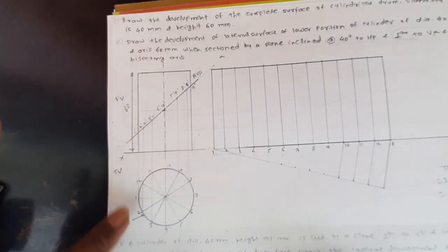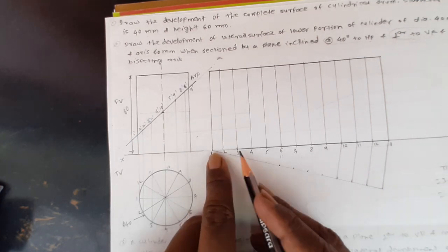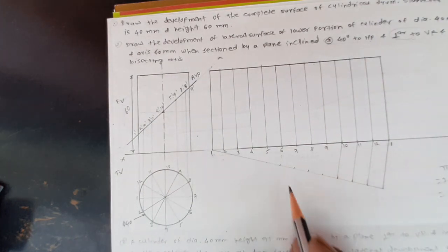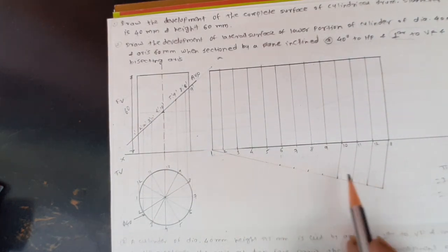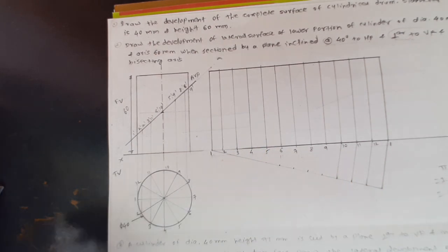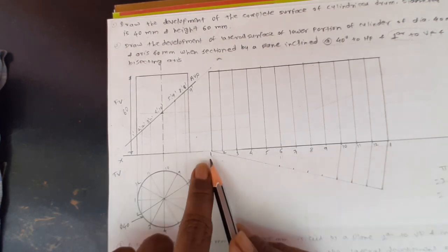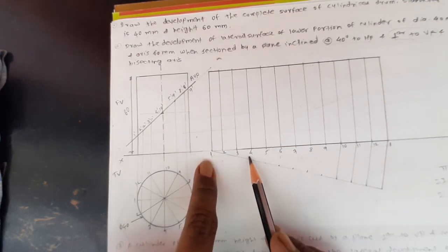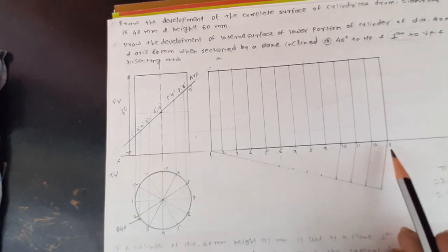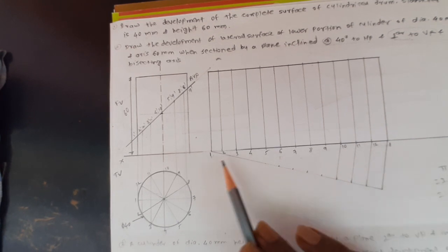Now here I made the 12 equal parts of a circle. So similarly here I make the 12 equal parts of this rectangle. We can use this method also that we have already learned in class. Now you have to repeat these notations again over here. So this is point 1, 1 2 3 4 5 up to 12, and the last one is again 1. All of you just remember this, the last point is the first point itself.